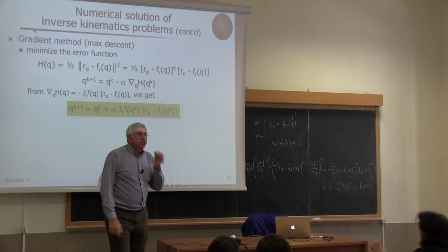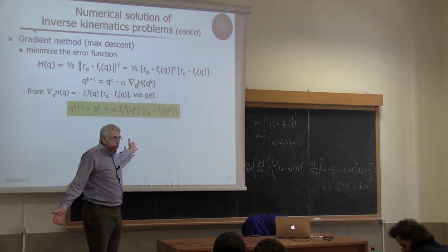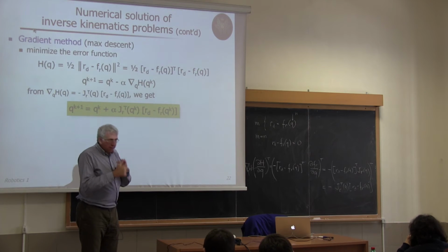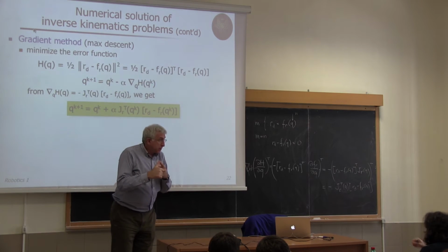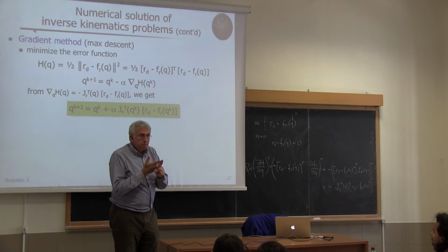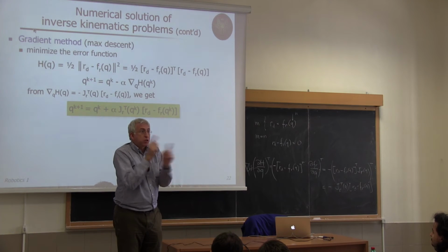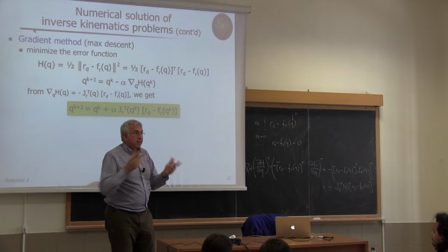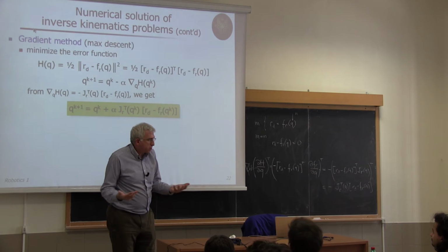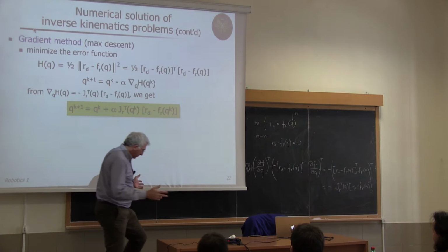Even if the Jacobian is non-square, this makes sense. It's the transpose of the non-square Jacobian. It's just exchanging rows and columns. Okay, so it's insensitive apparently to singularities. Works in any case, square or non-square, and it's simpler because transposing is an operation at cost 0. If you have the Jacobian, it's just considering the index exchange of the rows and columns, while doing the inverse is something that costs in terms of computation, even if the inverse exists. Beautiful. 3 positive aspects.